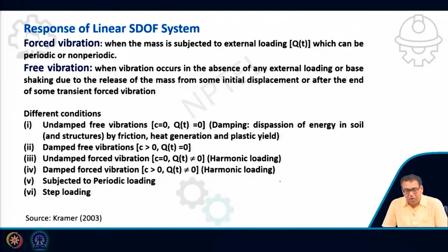It is when the vibration occurs in the absence of any external loading or base shaking, due to the release of mass from some initial displacement or after the end of some transient forced vibration. That means it vibrates in the absence of any external loading. So that is called free vibration.